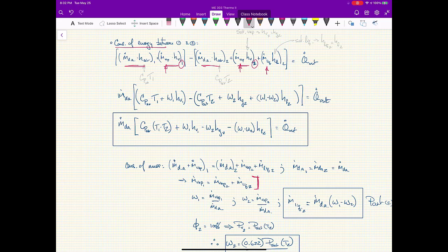So I think that follows directly. And so these are all the energies being considered between 1 and 2, and that's got to be equal to the rate at which heat is being extracted between 1 and 2. The problem did tell us how much that was, so this was a given. I think it was 11 tons that we were given for how much heat is being removed.